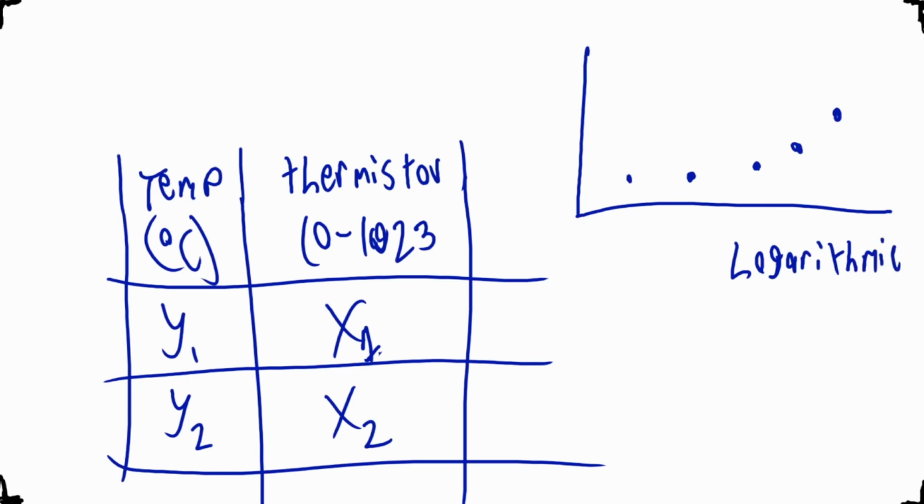I'm tired. I don't know why I had to bother writing out that word. Anyway, logarithmic trend line, specifically because the relationship of a thermistor between its resistance and its temperature is a logarithmic one. The shape that these points should form, if you've done your experiment or your measurements correctly, should be a logarithmic line. So if you add a logarithmic trend line, Excel should add something roughly like that, where it's forming a logarithmic shape that fits those points.